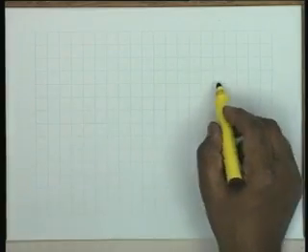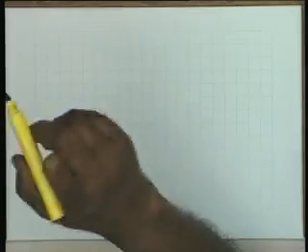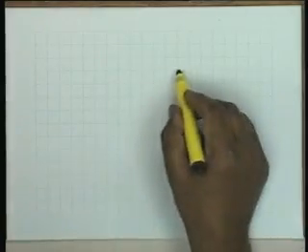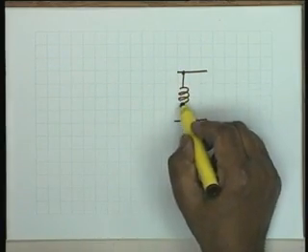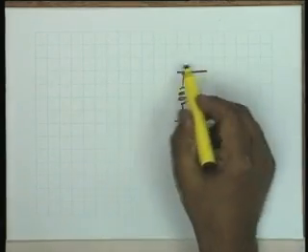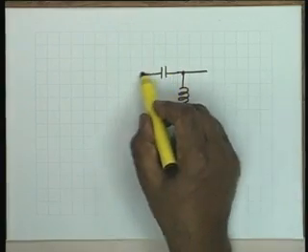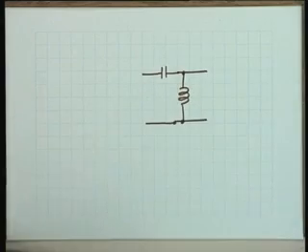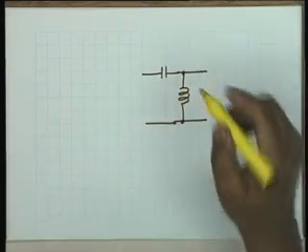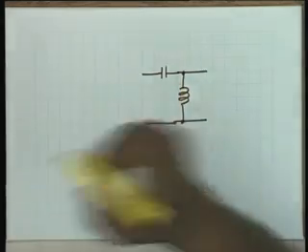Okay. At S equal to minus 4, poles. Transmission zeros are 2 at the origin and 2 at infinity. Now 2 at the origin, mind you, we are developing Y22. So we start from this end. 2 at the origin: 1 can be an inductance in series, and 1 can be a capacitance. Inductance in parallel, in shunt, and a capacitance in series. These two will take care of 2 transmission zeros at the origin.